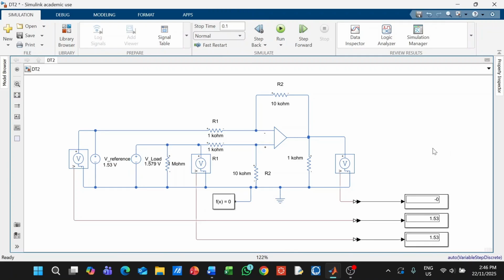In addition, since the load cell is actually a Wheatstone bridge constructed by only using resistors, to eliminate the loading effect, a 1 mega ohm is added to increase the output impedance of the load cell sensor. In other words, we increase the input impedance of this signal conditioning circuit.